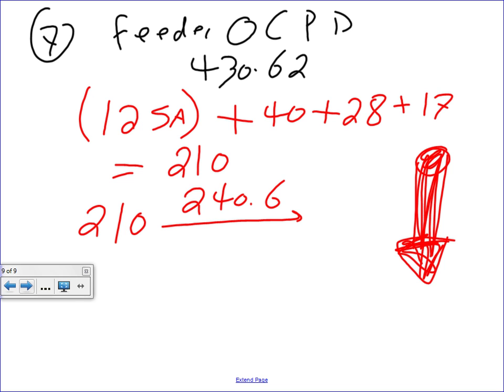If it's not a standard, where did you get the string of 40, 28, 17? That's from the full load amps, from the NEC Codebook. But I was thinking we're supposed to use the overcurrent protection values. Oh, you take the largest overcurrent protection device, and then you add to it the full load current for all the other motors from the code.